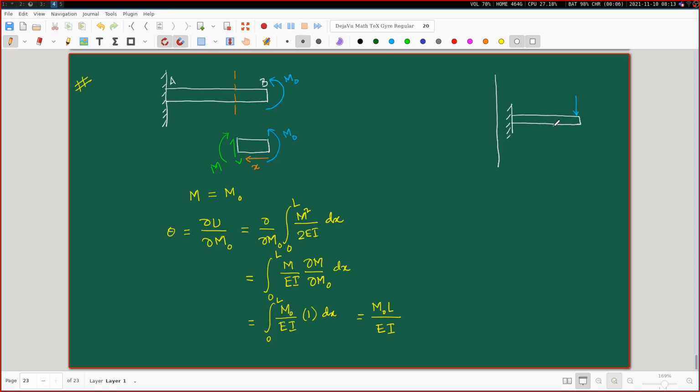So in the spirit of what you just said, suppose I ask in a very similar fashion that this situation is given and I am interested in finding the deflection at this point, at the midpoint or any distance within this beam, then what will you do? Same issue. Here I was asking about the slope, but there was no moment. Now the structure is the same, the loading is the same, I am asking about the deflection at some other point. Virtual force theorem: put a virtual force, then find the expression for the total strain.